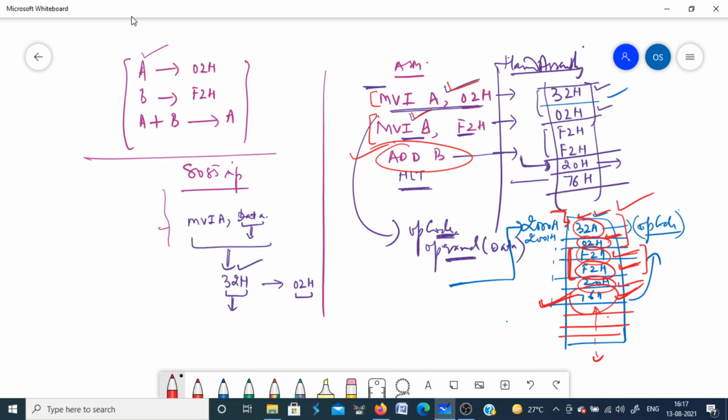And the processor does not differentiate between the data and the instructions, mind it. You can have some binary code, say 0 1 0 1 0 1 0 1. It can be an opcode, and it can be data as well. Whether it is an opcode or data, the processor will not differentiate. But the first byte that it fetches is always an instruction. It cannot be data.